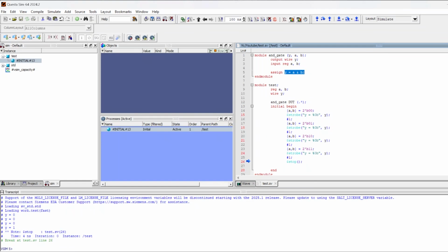So sometimes in some of the contexts, this becomes quite confusing. So for that particular reason, SystemVerilog introduced logic. And now we will go through logic. So for most of the cases, logic replaces both the reg and wire data type.